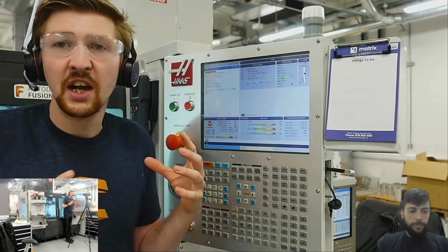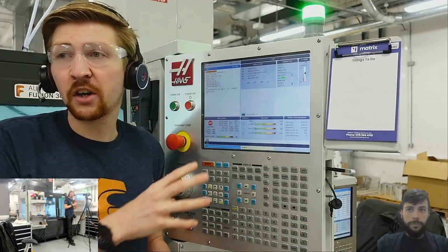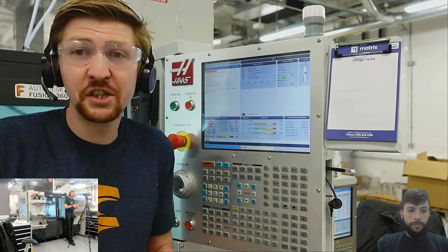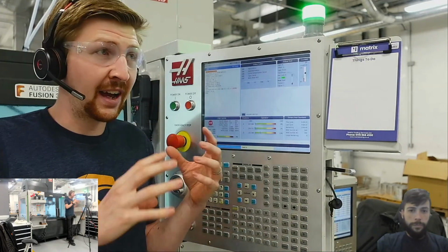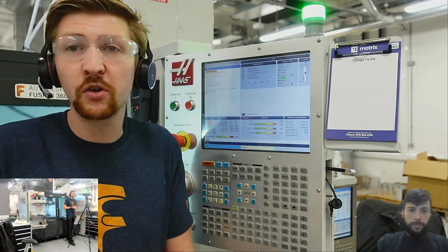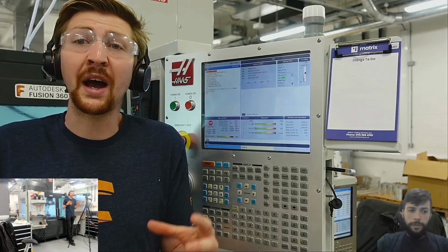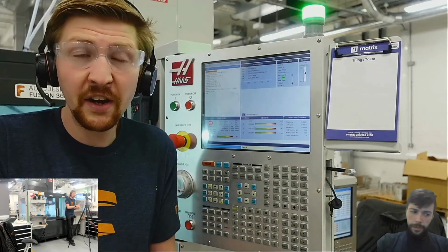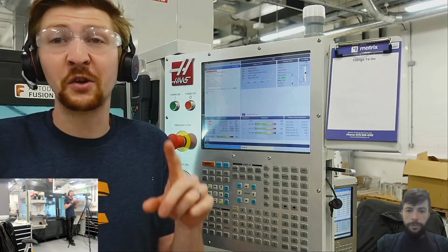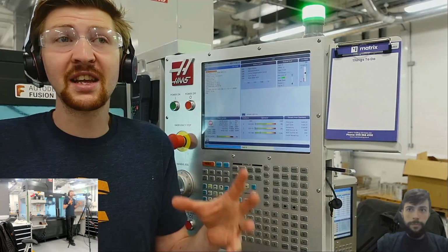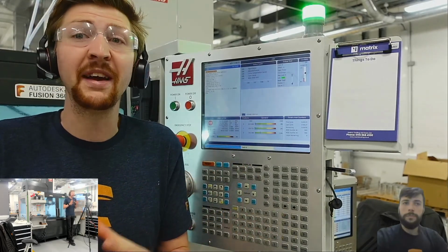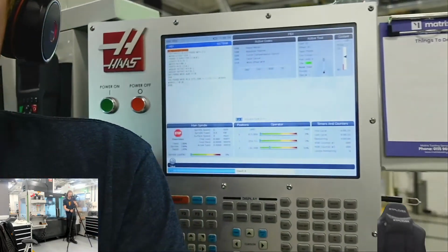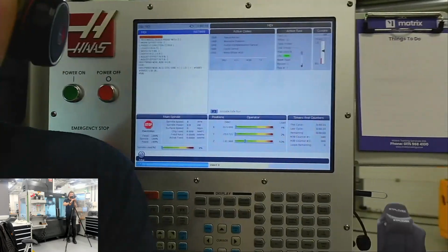We've got empty spaces on our controller that we can store and do things with data, be that calculations or printing out. On a HAAS and other FANUC type controllers, they're referred to as macro variables. On a Siemens, they're called R variables. On a Heidenhain, they're called Q parameters. So each machine calls them a different thing, but in essence, they all do the same kind of job.